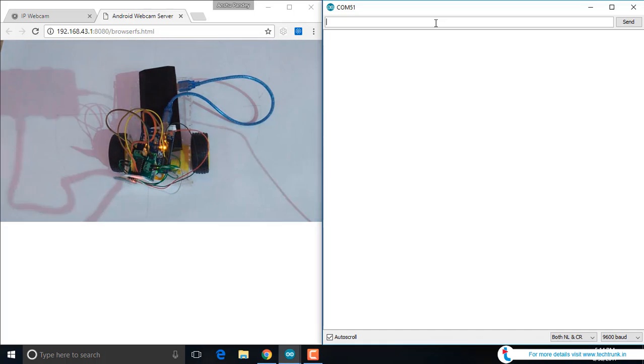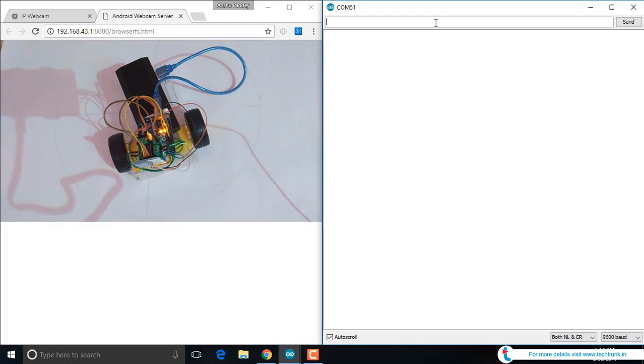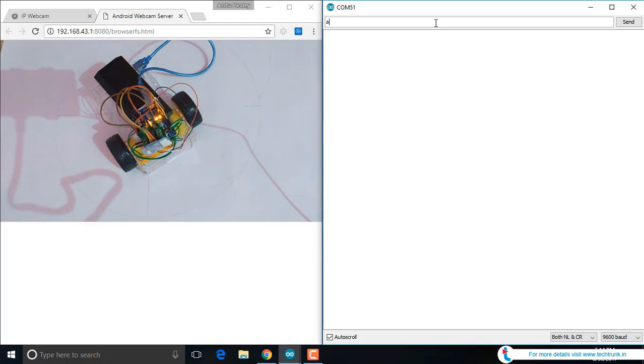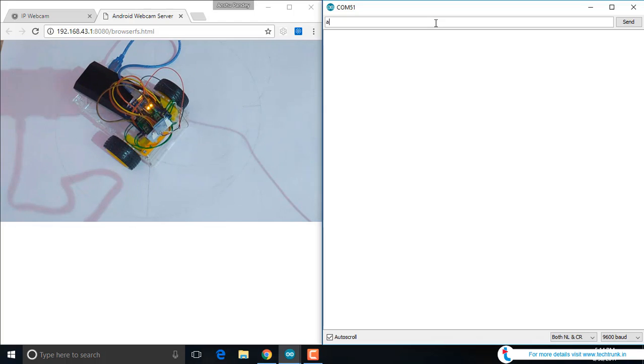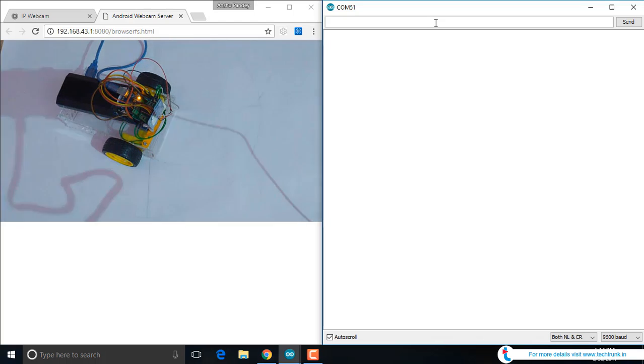We'll again send the robot the signal A, second A, third A, fourth A. You see after 4 A's it is taking a turn of 90 degrees, and that shows that A, that is 500 milliseconds, for this sort of motors is going to give a turn of around 22 degrees, and 4 multiplied by A is going to give a turn of around 90 degrees.